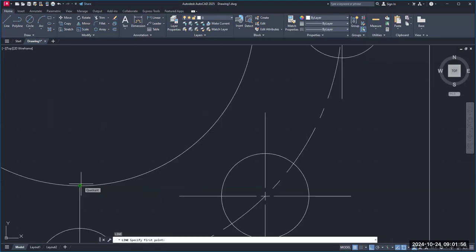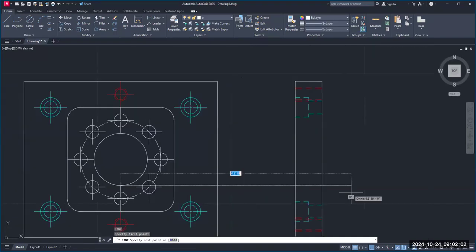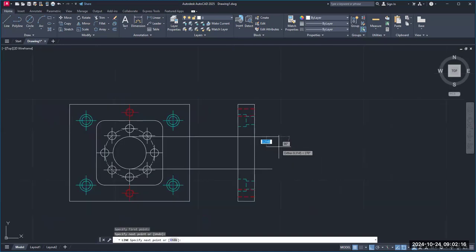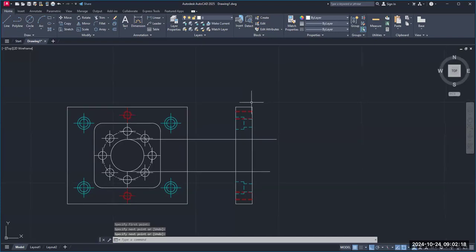You'll see a diamond appear, which drag your line straight across here, enter, or click and then enter, and select line, 12 o'clock position, snap to it, drag your line over, click, enter. Now we're going to trim this.